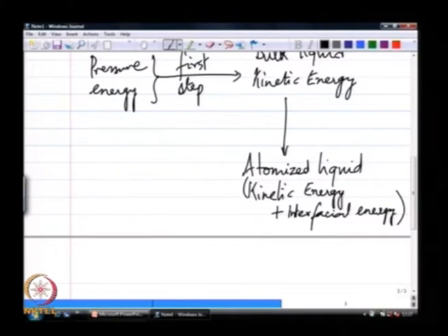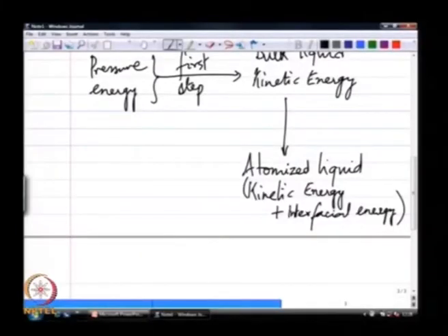I will give you just a simple thought example of a non-mechanical atomizer. If I take a drop of liquid and imagine I have embedded a tiny amount of some powder in it, some explosive at the center of this blob of liquid, and I explode it. So, there was a chemical energy in that explosive. At the end of it, if I can create stationary blobs without any dissipation, then all of the chemical energy in the explosive is completely converted into interfacial energy.